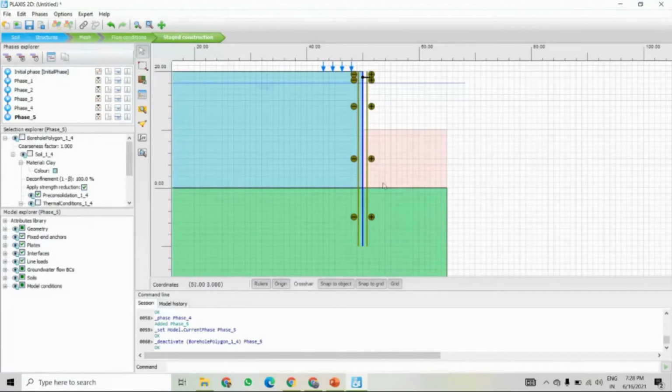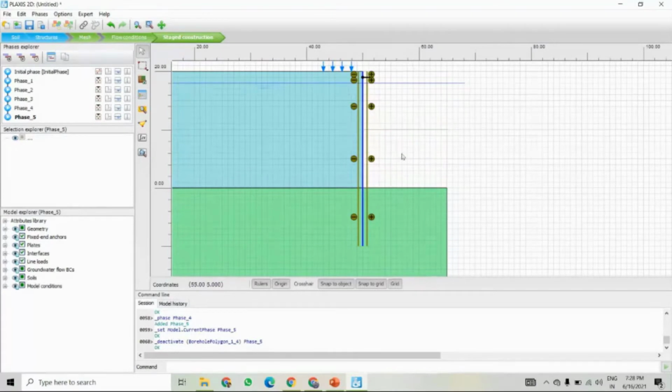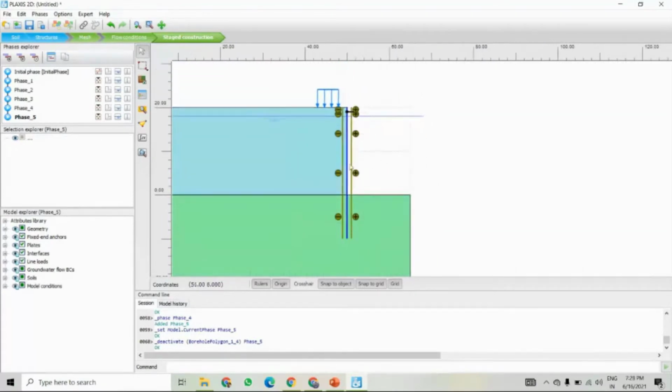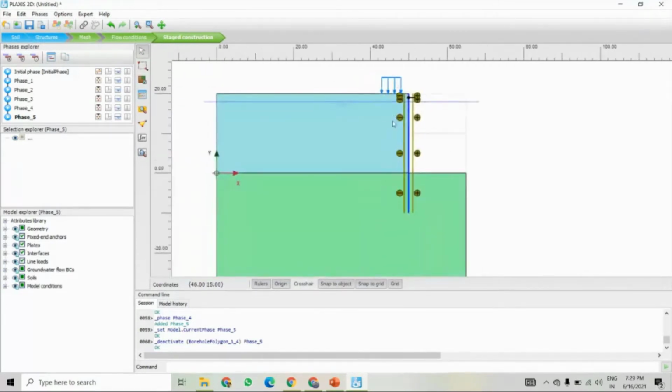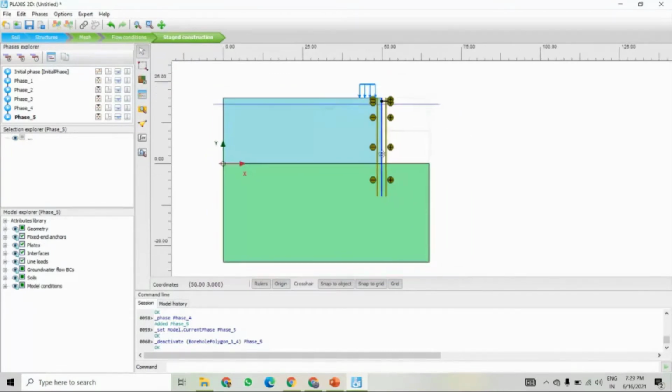Now we can put our tunnel here, and either we can create some foundation here first, then put the tunnel and then fill it again. But now we want to see what the effect of this load is on this area, or on this diaphragm wall, without filling this, right? So up to here, now we'll see the execution of the calculation.